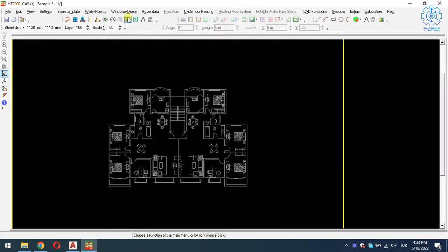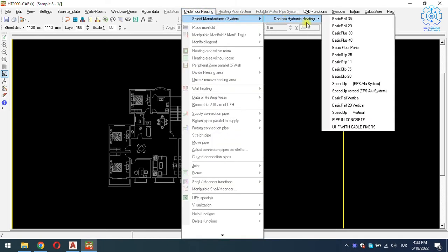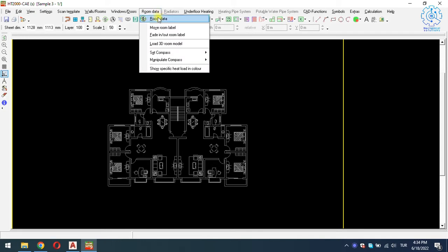At the first step I go to underfloor heating, select manufacturer system, Danfoss hydraulic heating, and we can select all of these systems. For beginners, just for drawing underfloor heating, I select basic floor plan. After selecting the underfloor heating type, I go to room data.